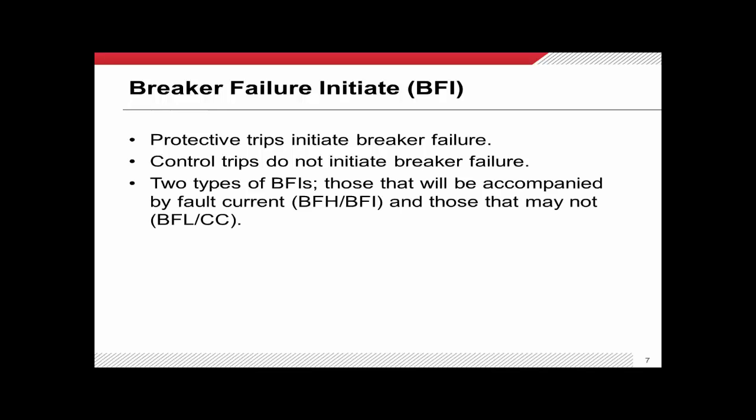Okay, there are actually two types of BFIs if you think about it. One of my clients differentiates these as a BFH and a BFL. The BFL is for the few kinds of faults out there, such as a sudden pressure relay in a transformer, that may not actually be associated with fault current. It's unlikely, but it is possible.